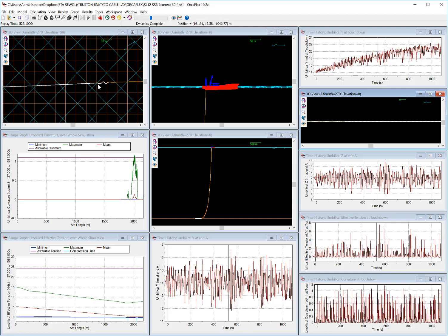The white indicates nodes which are on bottom, and the yellow indicates sections which are lifted off bottom. So here in this elevation, this section is all lifted off bottom, and these white nodes are on bottom. I'll set the thing playing, and we'll see this is playing real time, so the nodes on bottom are lifting up and setting back down, and we see this pattern of compression waves occurring on the bottom when the system is set back down.